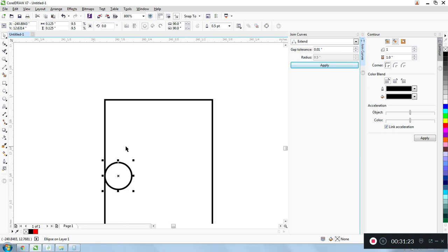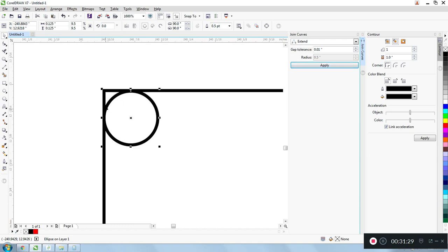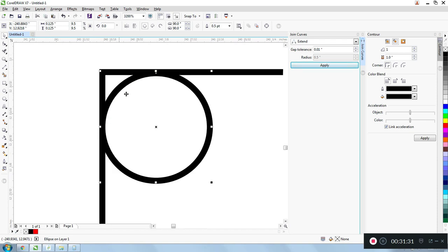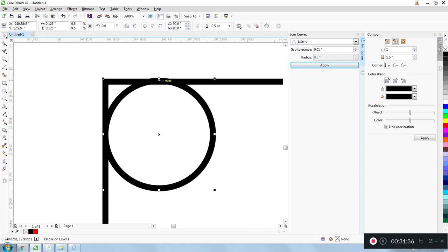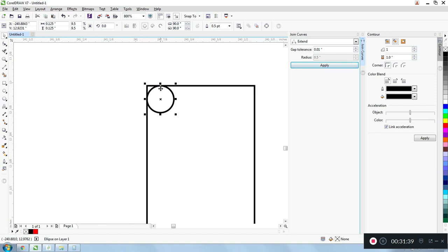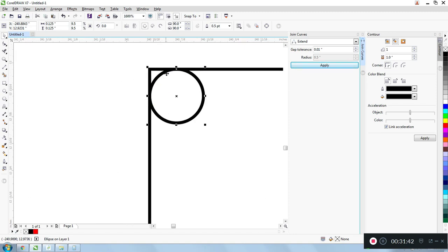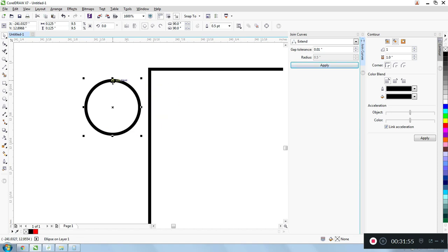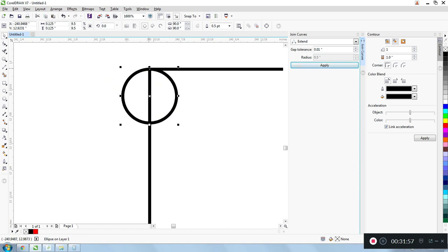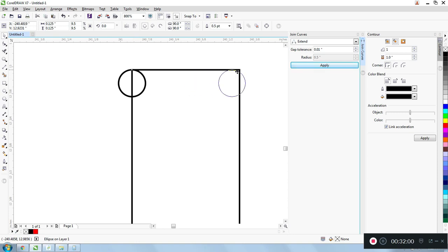And so you can see as it travels up, this is what your radius is going to look like on your corner here. That's not exact. I'll just drag that a little further. Still not exact. There we go. So that's not what we want, but we also don't want some crazy looking corners. So we need half of this to be dogboned. And what that is, I take the quadrant node here and I attach it to the corner. And I also do that here.